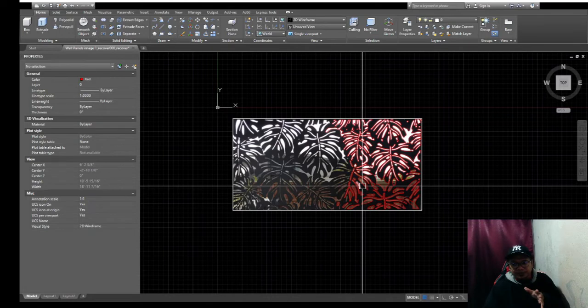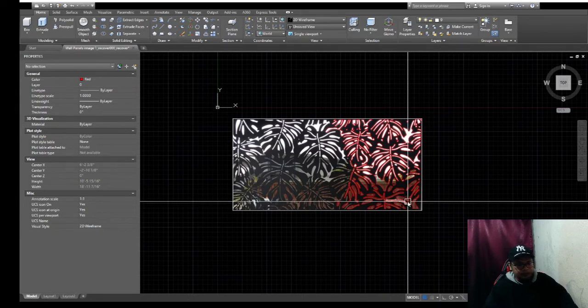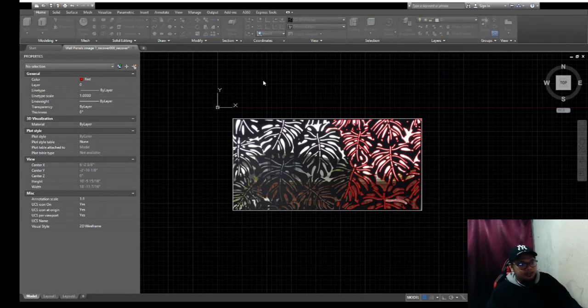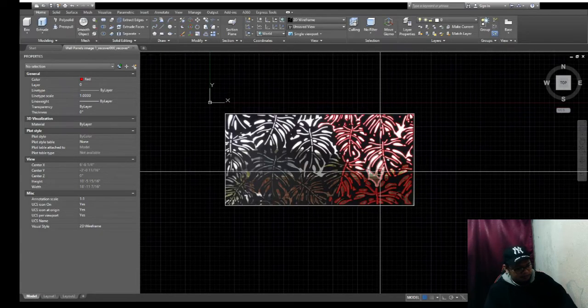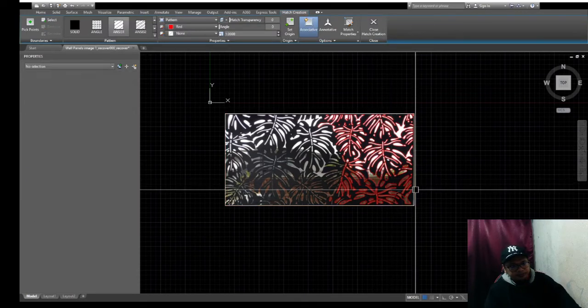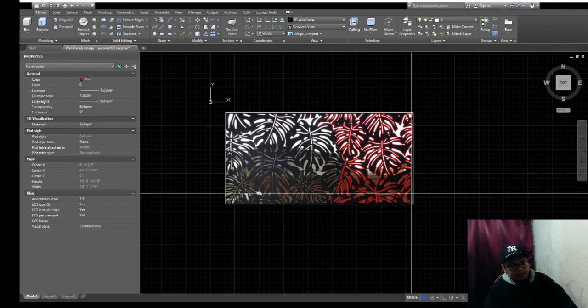So just for an example, you will need the hatch to solid LISP function. This is a script, and I think you can just comment down below if you cannot find it, but I can send it to you. This is what I use. This is a LISP. Load it, and then afterwards, you will create a hatch, outside.